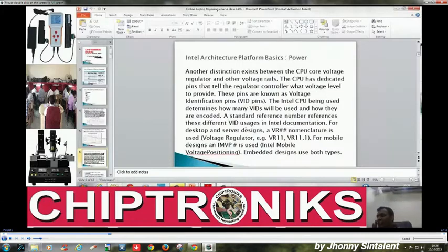So what are the three differences that we have talked about in a core voltage regulator? One is load line, second is DC tolerance, and the third is the VRM have VID pins. In the older voltage regulator you will find voltage identification pins, but in notebook designs, the newer kind of voltage regulator, you won't find dedicated VID pins. There is SVID data clock pin, right? This is missing from the other voltage regulators, right?